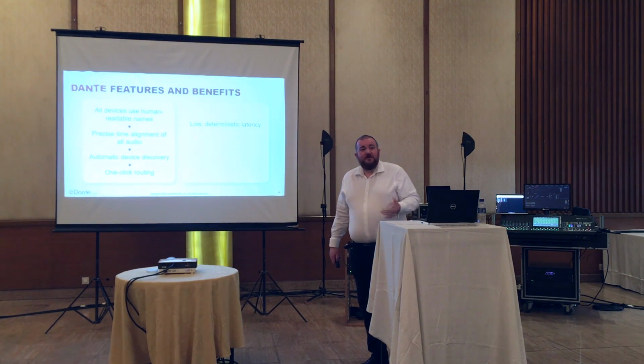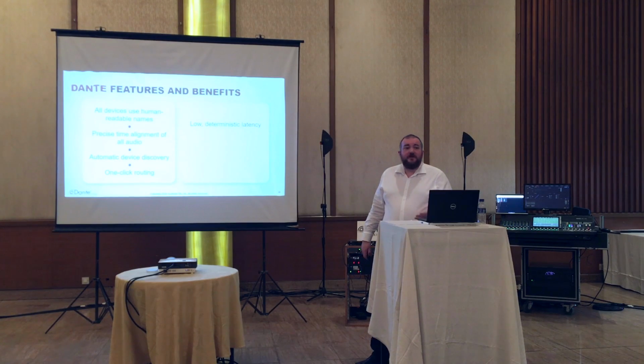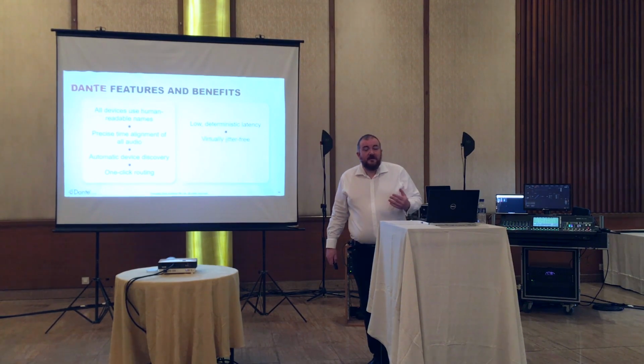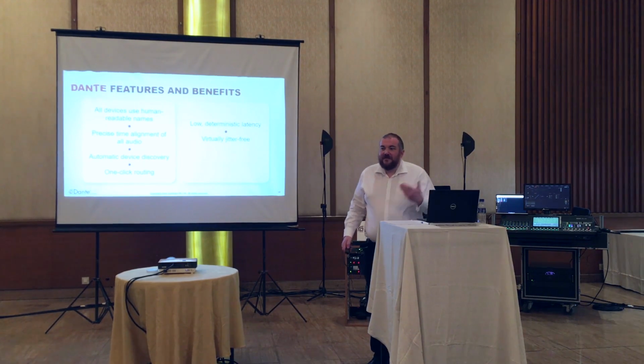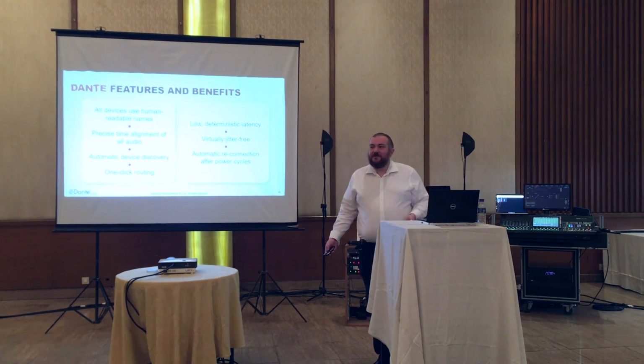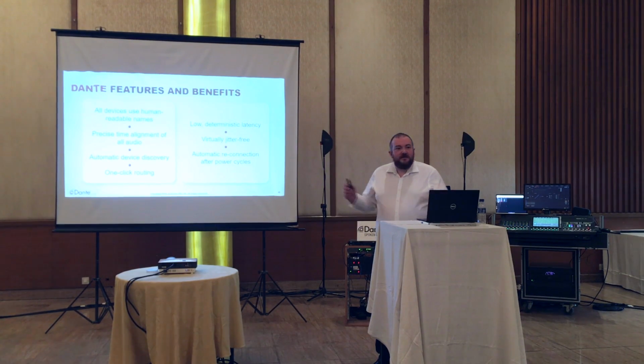And the other key things, because we're working in live audio production environments, we need to have low and deterministic latencies. So Dante is a deterministic latency, virtually jitter-free in the audio spectrum, and we can automatically reconnect. So if the power goes off, when we bring the power back on, because the relationships and the patching is stored in all of the individual devices, they'll come back up and try and get hold of what they were listening to when they were last working.